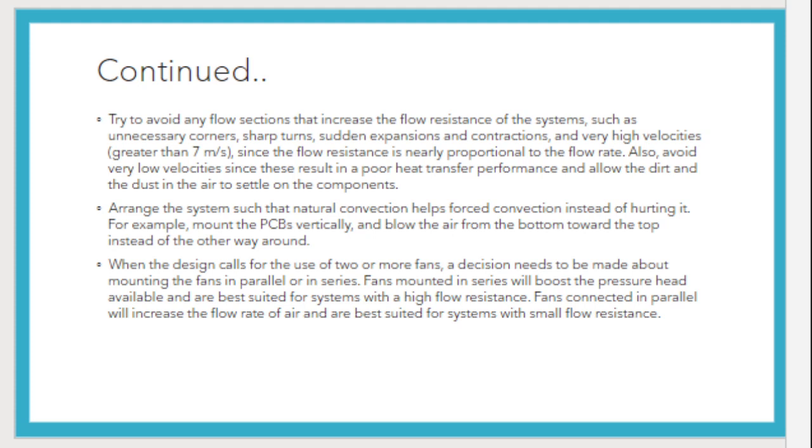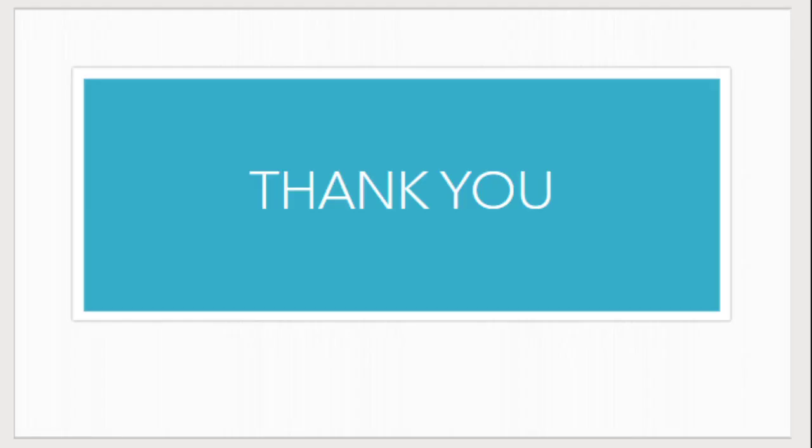Fans mounted in series will boost the pressure head available and are best suited for systems with a high flow resistance. Fans connected in parallel will increase the flow rate of air and are best suited for systems with small flow resistance.